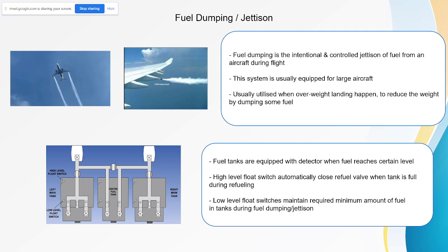When we land at KK, the weight of the aircraft minus the burned fuel should be this much for me to land. So it's all calculated, including my landing speed with the weight. If not, you will be overweight landing already. So this fuel dumping is not practiced for every flight. It's only for emergency.